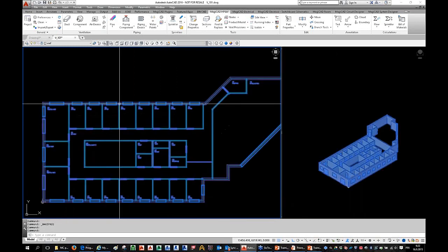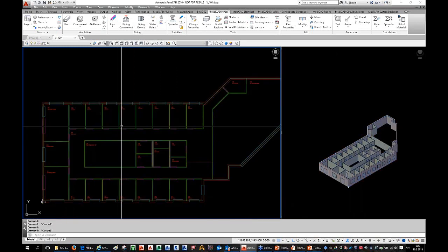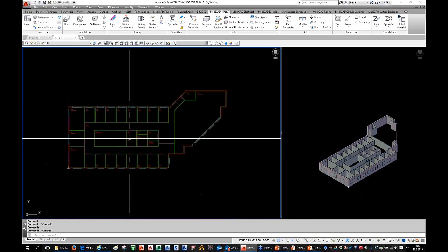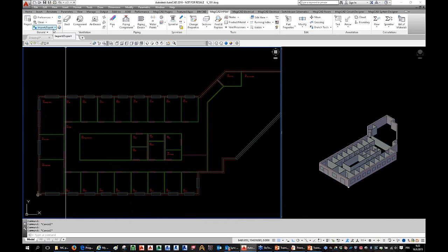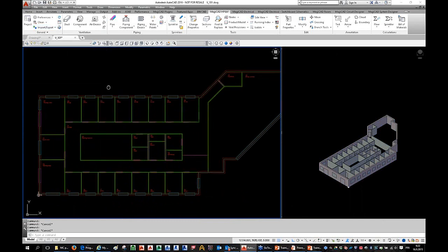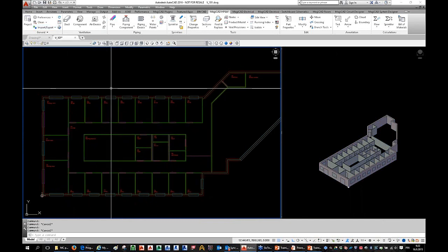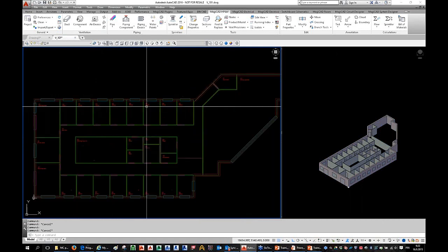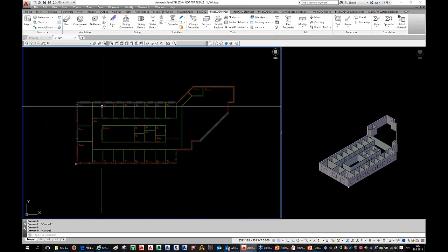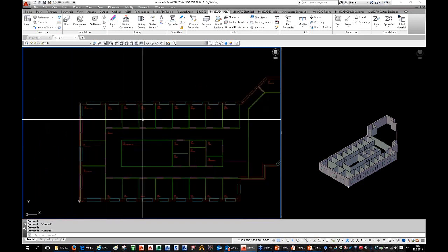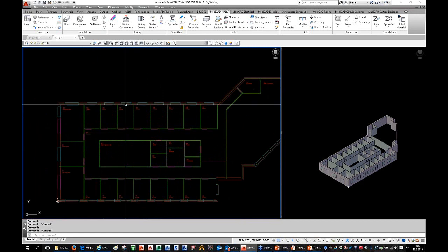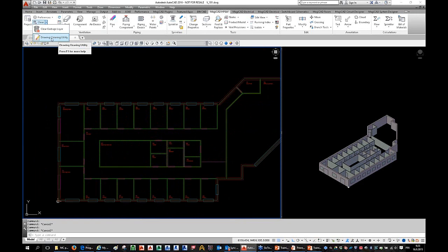So this is an external reference, so I can't modify this building now. But what I can do is use MagiCAD's drawing cleaning utility. So when you receive an architectural model, they are quite often not so clear. More than one color is used. So you can use the drawing cleaning utility function, which is found in the General tab.